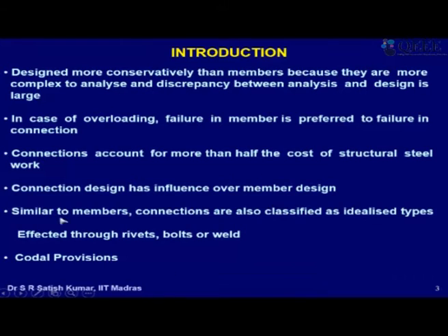And connections are generally done, for hot rolled steel, through rivets, bolts or welds. Riveted connections have become almost outdated, because to form the head of the rivet, you put a rivet through and then hammer it with a rivet gun so that you form the head. So the rivet has to be somewhat soft for making the head, and as a consequence the rivets can't take very high loads. They shear off at very low loads.